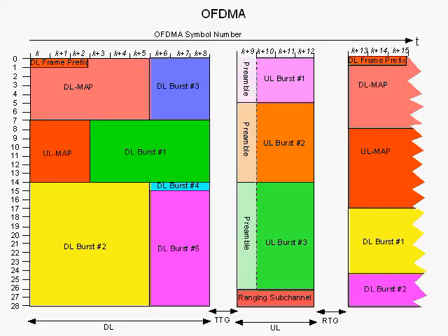We also have a comprehensive tutorial on OFDM multiple access. Here we show the downlink subframe and the uplink subframe in a TDD frame for OFDMA. We will go in detail as to how the carriers in, for example, a 2048-point FFT are arranged into subchannels, and then each data burst is arranged in terms of a subchannel offset, the number of subchannels, a time slot, and number of time slots, which are OFDM symbols, in order to define both downlink bursts and uplink bursts.